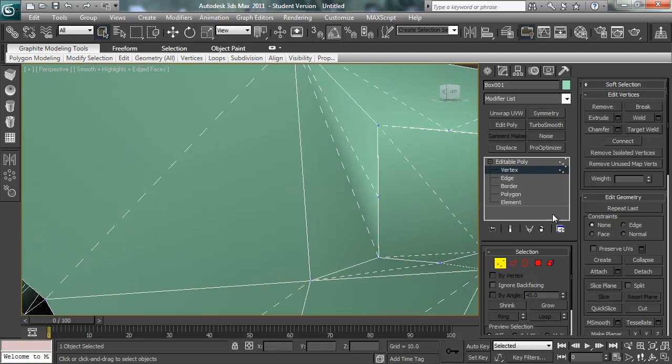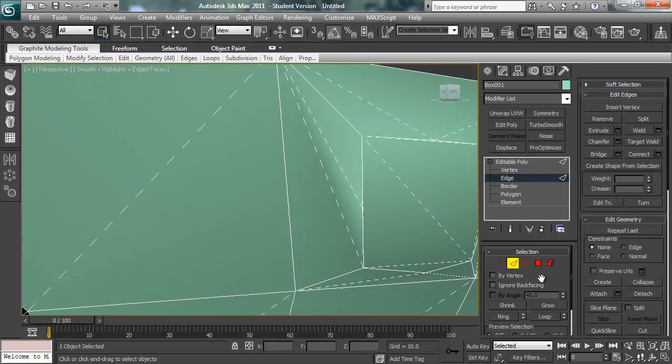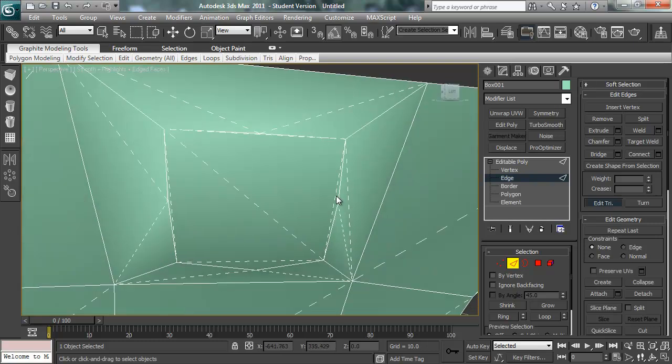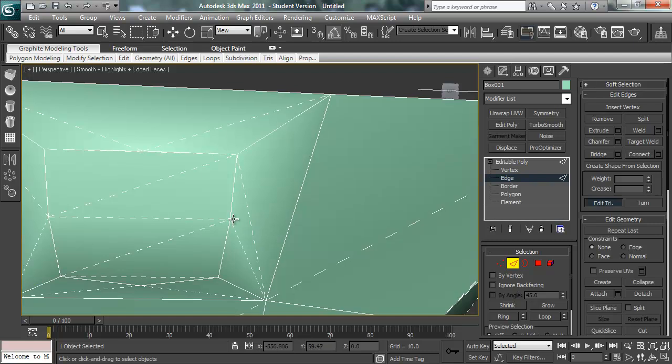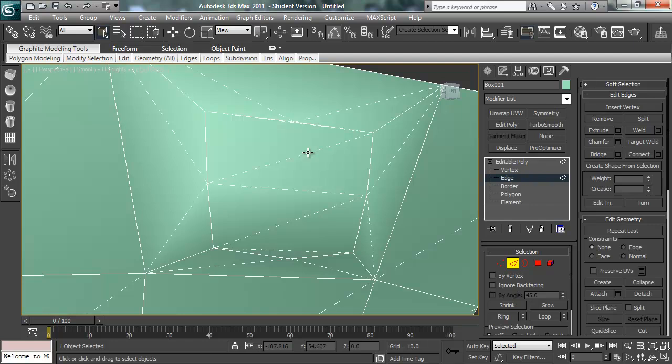edit triangulation because it's quite useful, and sometimes you don't want to just cut there. So if I go into edge, and under the edit edges section, click on edit triangulation and just click the ones we want, we can see that that's now much better smoothing because we've not got the thin triangles. You might also choose to go from this one right over to here, and that might work a little more how you might expect, and this one up to here. So edit triangulation is very useful, and you should be aware of how to use it.